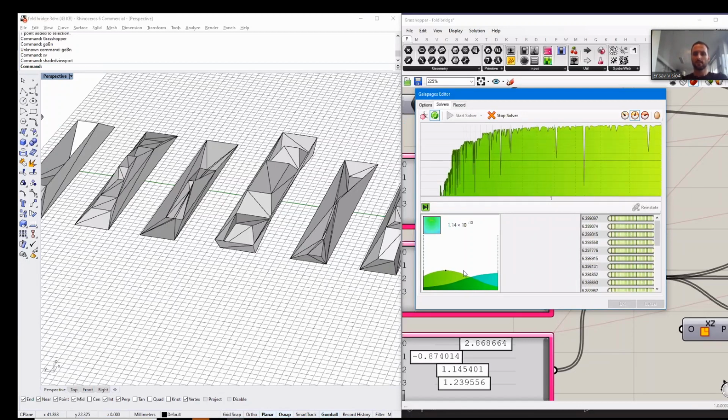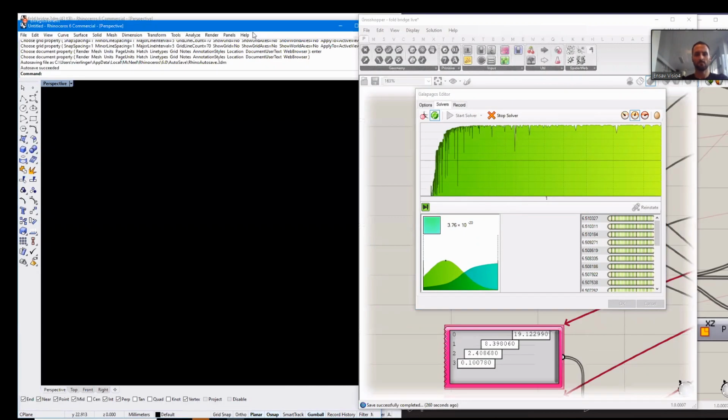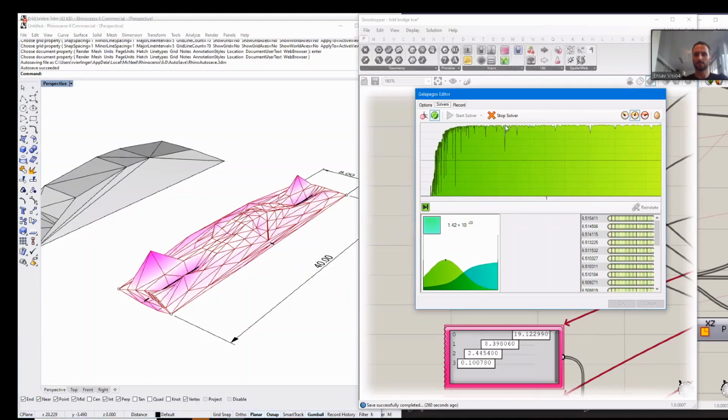This is the annealing temperature. So the higher the two bumps are, the green and the purple, the more converged the process is, in a way. Also, you see the number of changes in the goal value here. So this is my natural frequency. We had 0.4 hertz before in the random design. Now we arrived already at 6.5 hertz, which is a lot higher. So I'm just going to maximize the window again and see where it ended up by stopping the solver.